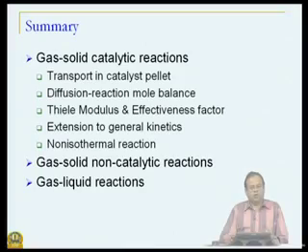We then wrote diffusion reaction mole balances for these reacting species. Now, the moment we say that we have diffusion and reaction, two different processes, and within diffusion there is internal diffusion and external diffusion, each of these processes has its own characteristic rate or time scale.